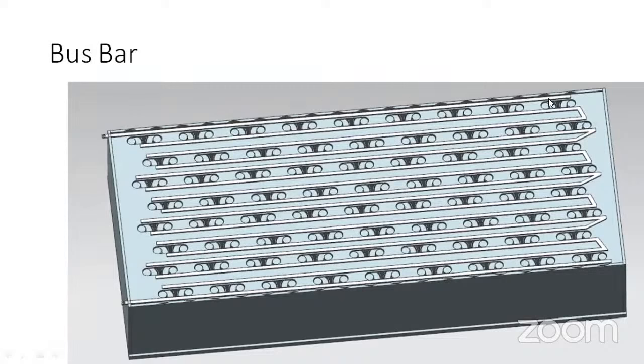So these bus bars are there. Now you can do spot welding. In case of spot welding, you have to keep this bus bar on the cells itself. And if you are willing to do wire bonding, then it would be a little bit on the side of the cell, so that the wire will be bonding here and it will be touching here.